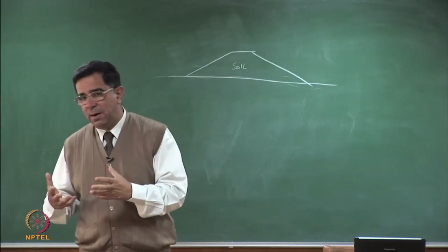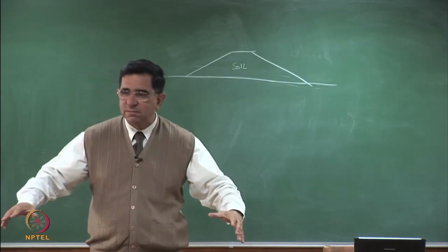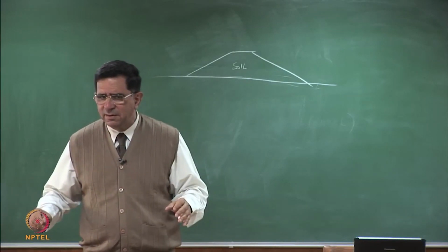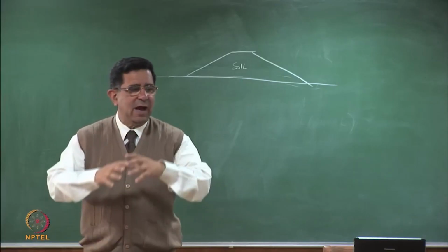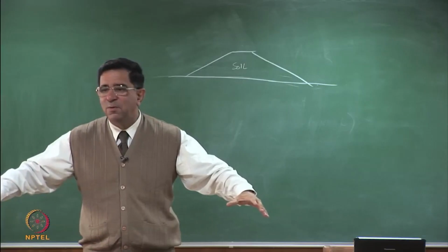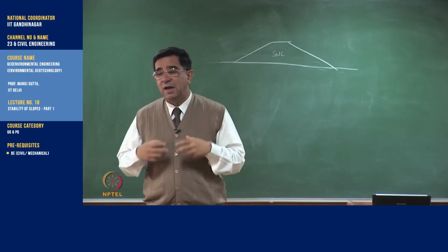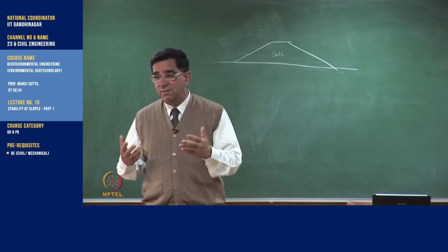So please do remember that the angle of repose tells you the phi dash of a material. Is that right? But if you have very high water content sludge, it will become very low values. Same sludge, when it is dried, will have higher values.